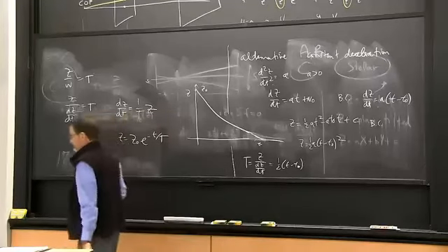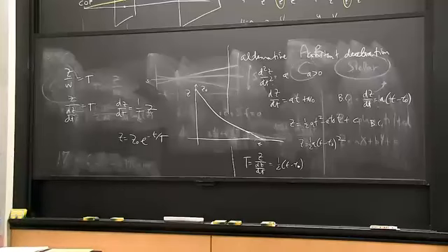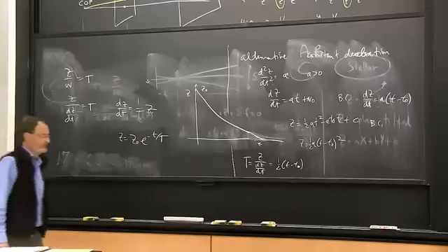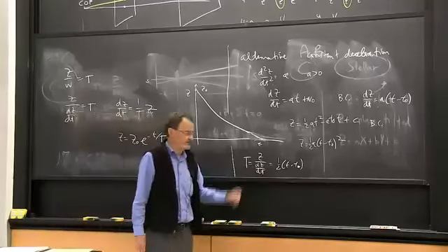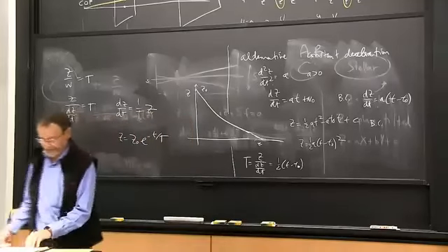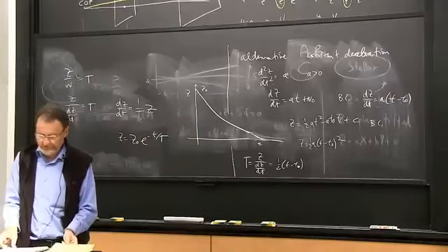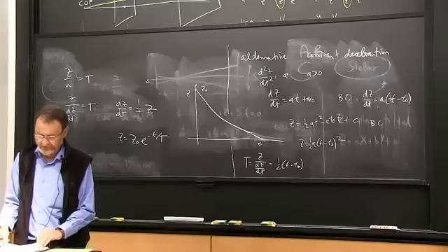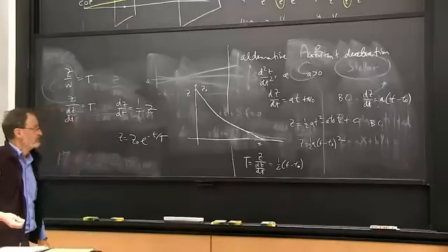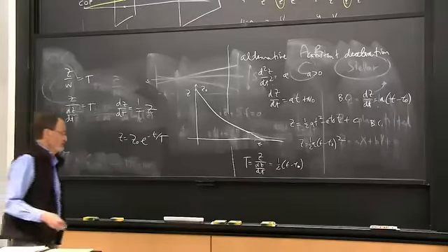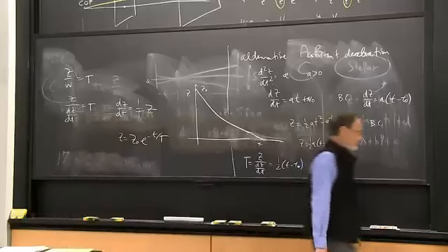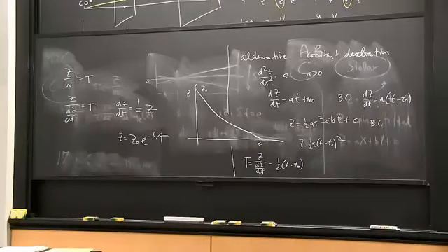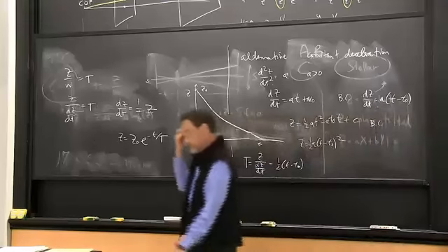Over here, of course, the time to contact would be t minus t0, but because of this constant acceleration control, we get that result. Anyway, it's just a way of comparing constant time to contact control with a more traditional approach. The more traditional approach is somewhat more fuel efficient, but it's much harder to implement. It requires accurate estimations of distance and velocities.